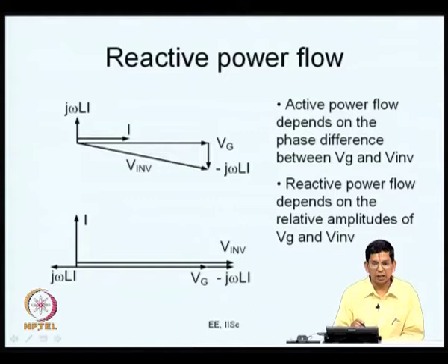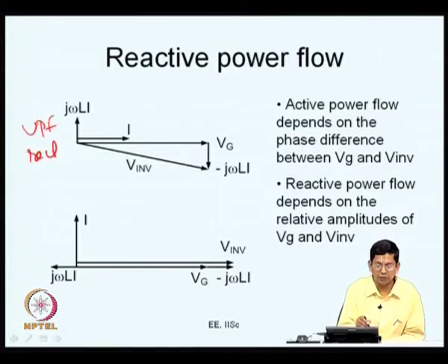Here we found that the current can be either at unity power factor or at 180 degree phase difference. It can be at any arbitrary phase angle, and one thing that is of interest for us is to see how you can do it at 90 degrees leading. So, the current is 90 degrees leading. In the first case, this is what we saw in the case of a UPF rectifier. Now, you want to pump reactive current into the mains. So, you want your current to be leading the grid voltage by 90 degrees. The corresponding j omega L is as indicated here and minus j omega L is as indicated here, and you have your V inverter and Vg of the same phase, but V inverter is greater than Vg.